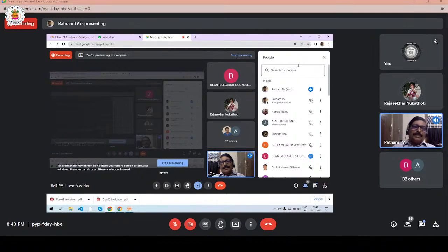Particularly the diesel engine funnels produce high temperature exhaust gases, and due to that, they can appear in the thermal camera. That can be suppressed by using infrared suppression devices, using some water cooling, mist like things. NSTL has developed such a device, the IRS, infrared suppression device, for both diesel engines and turbines.